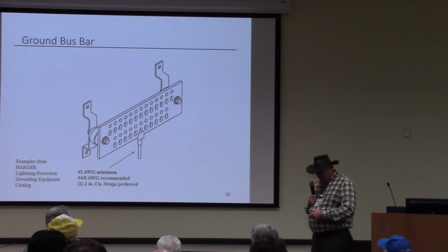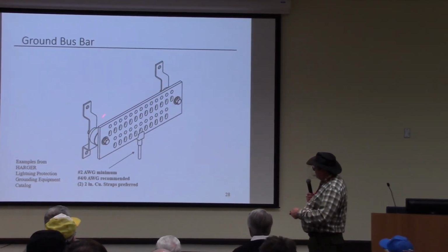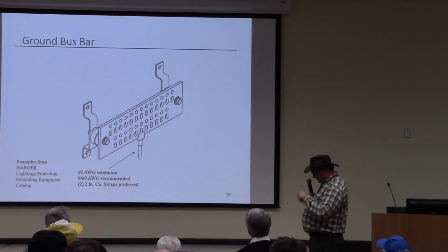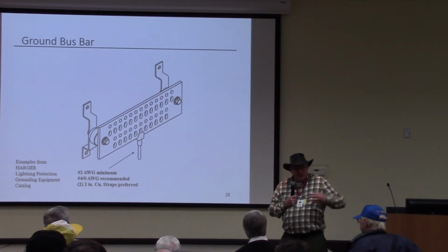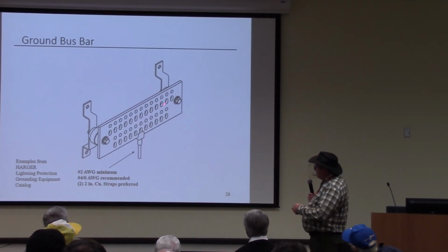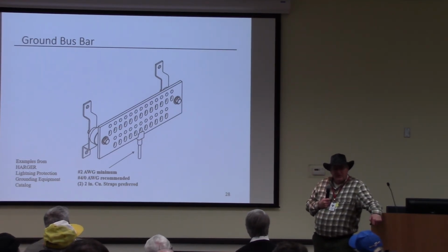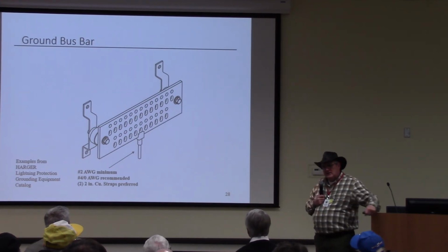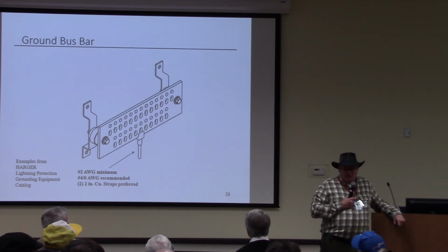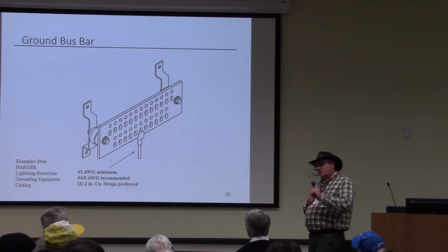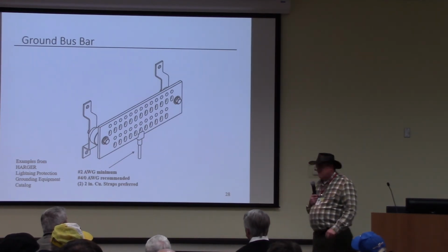One of the products that are out there is this mounting bus bar. This was normally found outside the facility, right where the cable harnesses are coming into the facility. This is where you would mount your arc gap, where you mount your surge suppression, and all to try to divert the energy from coming in on the center conductor. Because as the current is flowing in the shield, it is inducing a current in the inner conductor as well, and you're getting a voltage potential between those 2 points, and that's what can damage your radio as well. Okay.